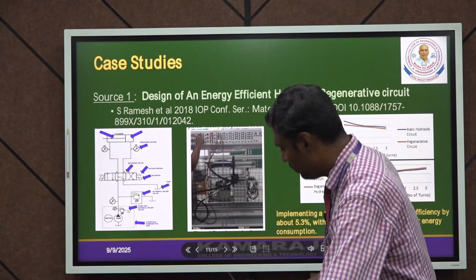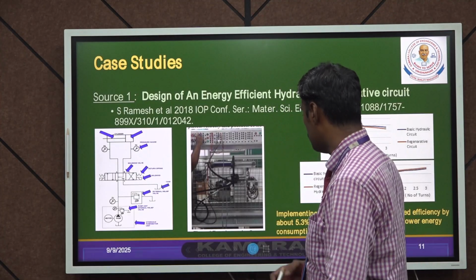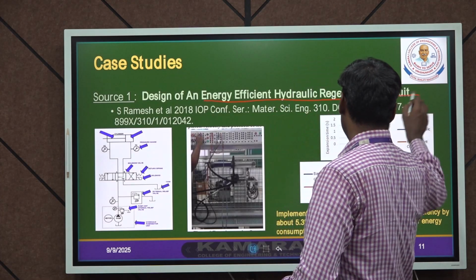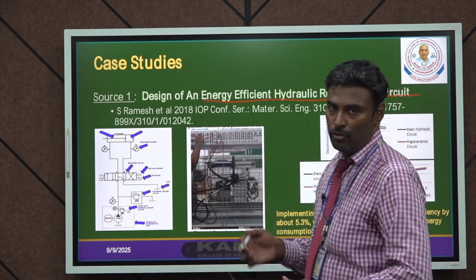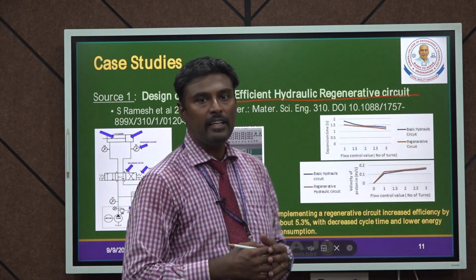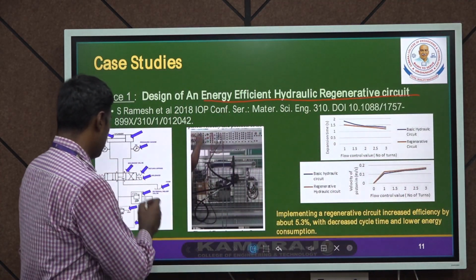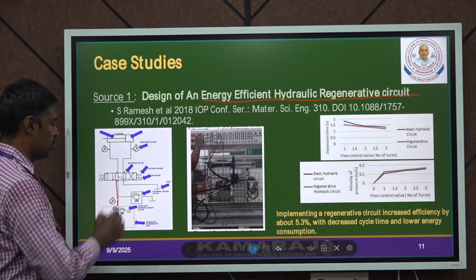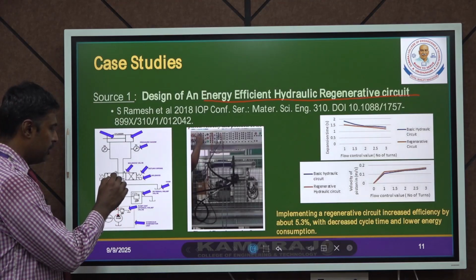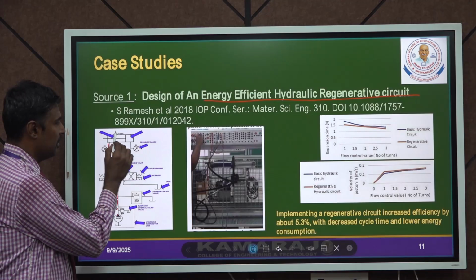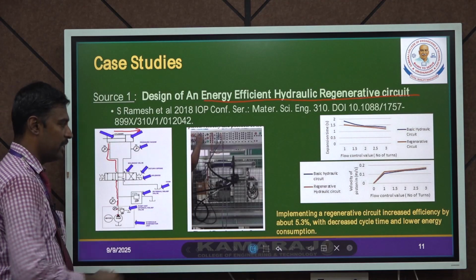Case study 1 is the design of an energy efficient hydraulic regenerative circuit. First, I will explain what a regenerative circuit is. If you look at this, the pump is delivering the fluid from this position to this position. Here the fluid is moved to this double acting cylinder, and the cylinder gets extended in one direction.